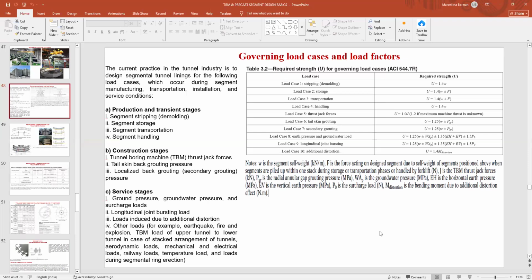Because in the middle of the production stage, I cannot change the reinforcement arrangement. I can make additional reinforcement wherever I think it might get affected. I can put some additional chair bars or some additional parts also. But generally, we try to make it epoxy coated, or try to make it within a plastic sheet cover.